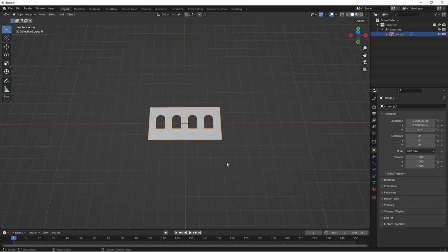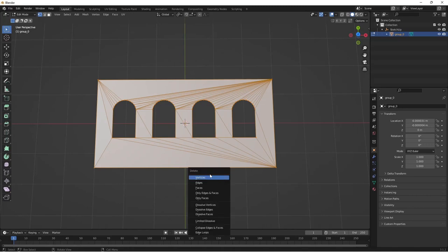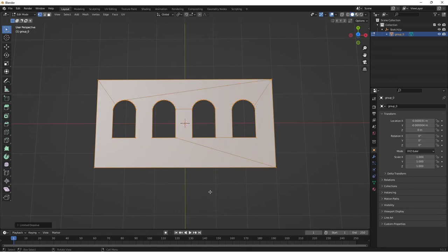Click on the wall. If we press tab now, the menu changes down the side, because we've gone from, look at the top left, object mode, and then tab, edit mode, and it just tabs between the two. So now we want to press A again, and all these vertices here, all these lines are going to mess all the geometry up. So what we want to do is simplify it basically. If you press X, you'll come up with a delete box, and you've got different things you can delete. What we want to go down to is limited dissolve, and if you click on that, now Blender needs to attach itself to the outside walls.